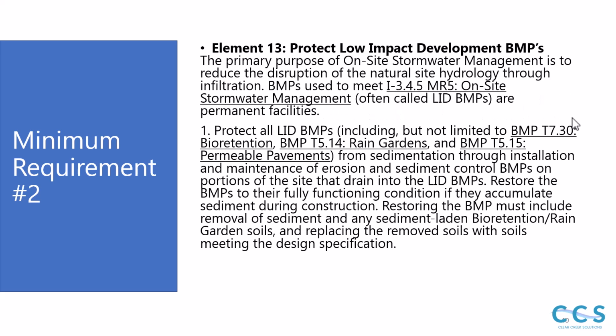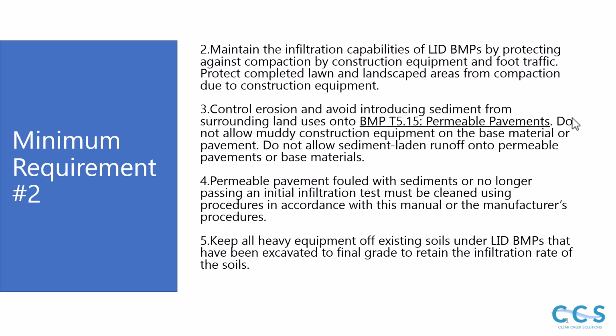And then finally, element 13, protect low-impact development BMPs. The primary purpose of the on-site stormwater management is to reduce the disruption of the natural site hydrology through infiltration. Protect all LID BMPs, such as retention, rain gardens, and permeable pavements, from sedimentation through installation and maintenance of erosion and sediment control BMPs on portions of the site that drain into the LID BMPs. Maintain the infiltration capabilities, control the erosion.